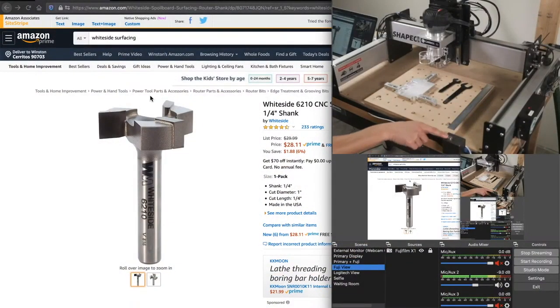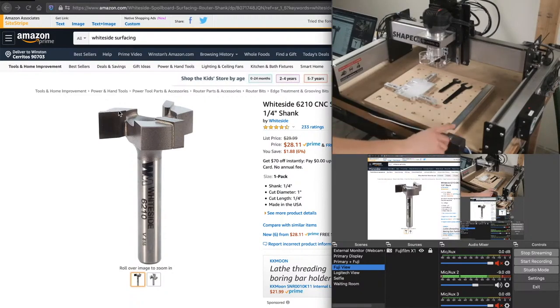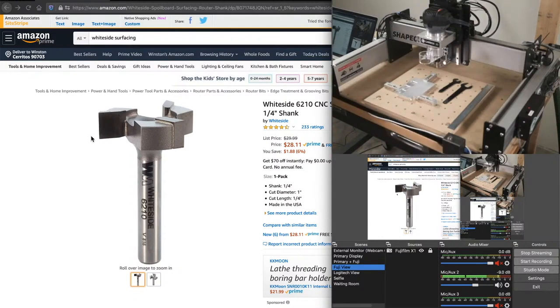That being said, there is a slight chamfer on the bit setter pin, and that could cause an incorrect height to be detected. The best thing to do if you have an oversized tool like that is to shift the bit setter so that it's offset, not perfectly centered with that depression in the surfacing tool, so that one of the teeth is guaranteed to hit the top of the pin. Not always practical, but you can do that. I have mine offset by about 1 or 2 millimeters, and when the bit setter goes to touch off, I make sure I rotate this tool so that one of the teeth is directly over the pin.